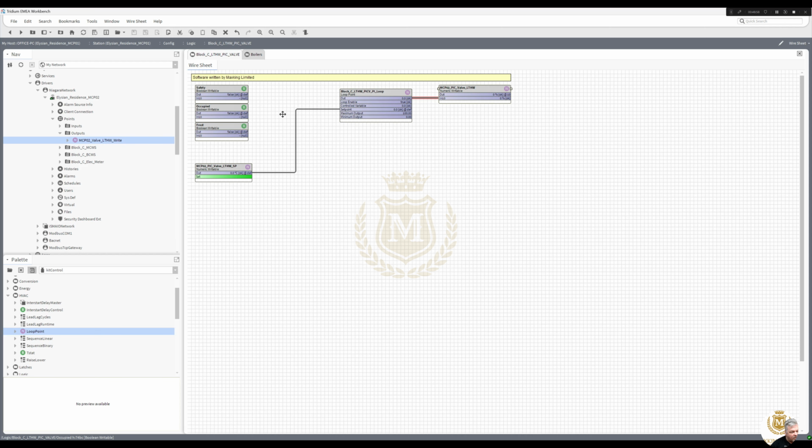And we have got safety, frost, occupied. So occupied or frost. So we can put an OR gate and then an AND gate for the safety. Let's do it that way.